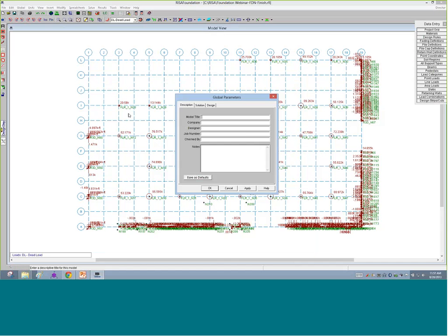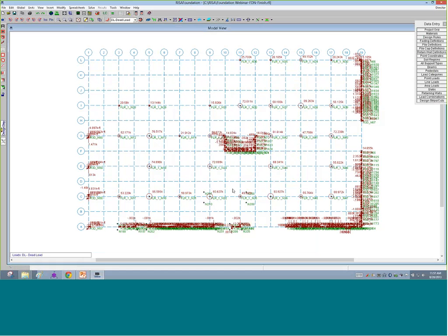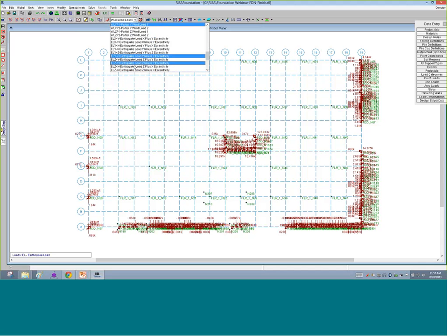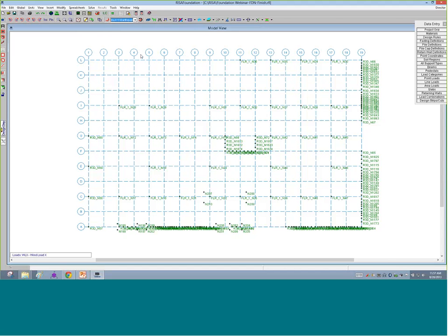So it solves, and you can see it brings across every single load I had from RISAFloor to RISA Foundation. And what's great is now it's categorizing them for me. So live loads, dead loads, earthquake loads, any loading I brought across. Earthquake in our case was ELX or ELZ direction. All of that information was brought across for us. This is really detailed as we go across there.